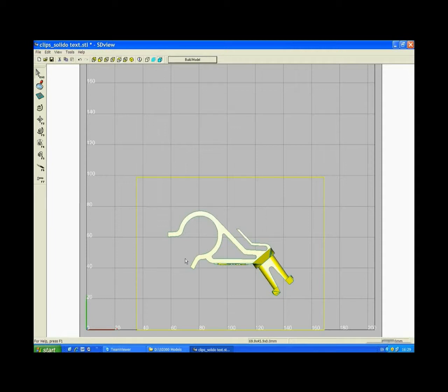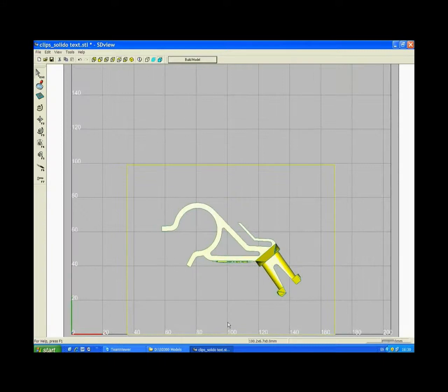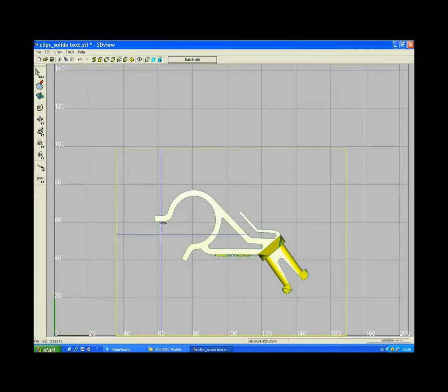The main objective is to first peel around the part and then empty out the areas at the end. We will now proceed to place peeling cuts and make sure that we seal all the areas. This will help us peel around the part freely, and then proceed to remove excess material from the inner parts.